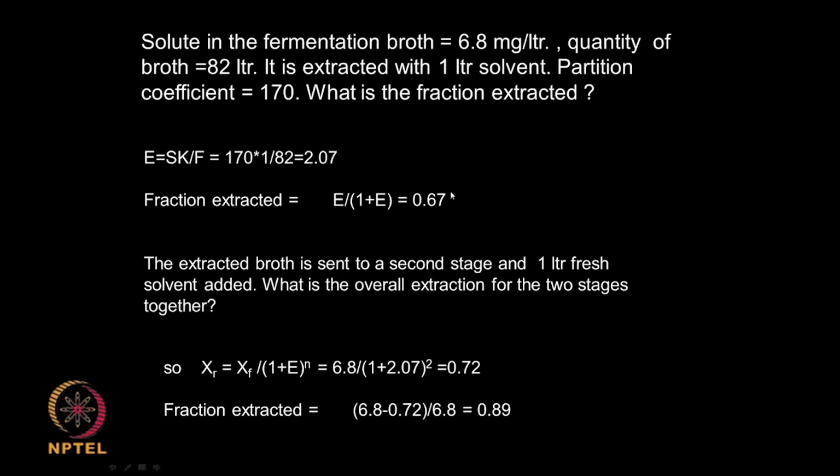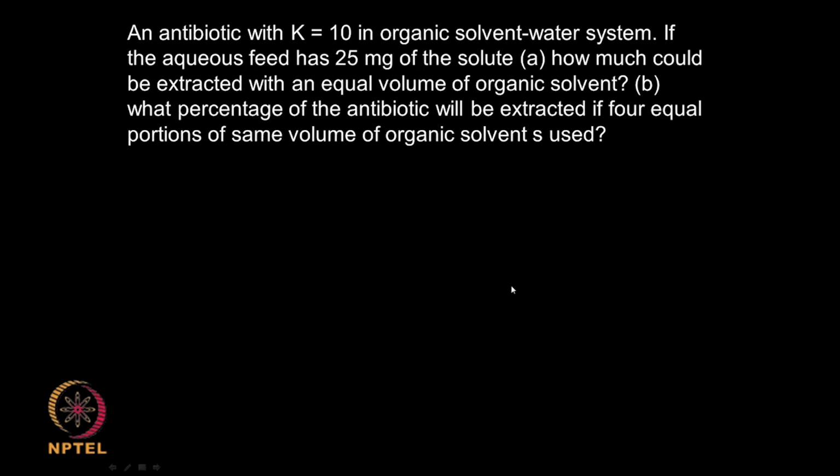So, in the first stage I am extracting 67%, and overall after the second stage I am extracting 89%. So, it is good to have 2 stages. But of course, I have used 1 liter solvent in the first stage and another 1 liter solvent in the second stage.